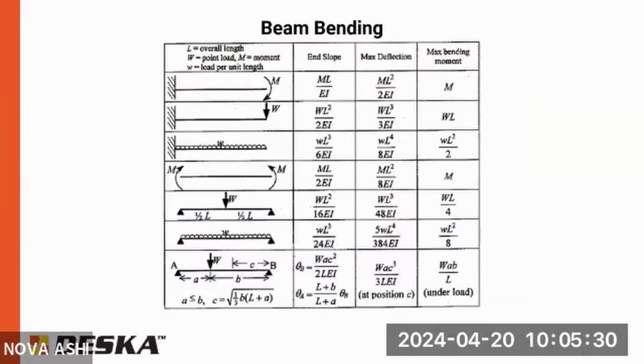In terms of beams, the purpose of a beam is to support something and span it from two supports, one support to another. In residential construction, pretty much all your beams are simple span beams usually, and there's a continuous load on top, like here in this diagram. And this is the formula for the bending moment of a beam. It's the uniform load times the length squared over 8. That's the bending moment. That's how much bending stress is on that beam.